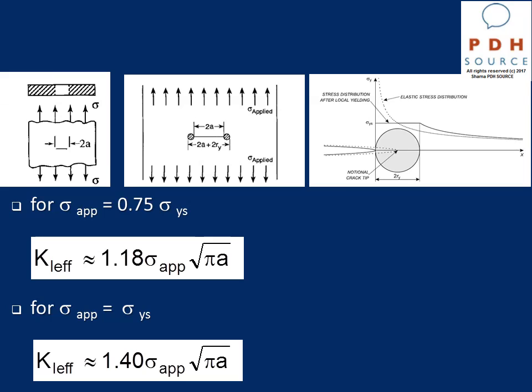So in summary, as a first approximation, we can use K1 equal to K1 effective, equal to a function of applied stress, the crack length, and the plastic zone size. This appears to be a reasonable engineering approach even for stresses approaching the yield strength, as we have shown here.